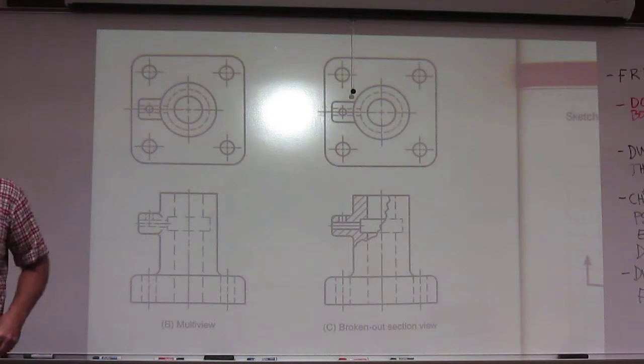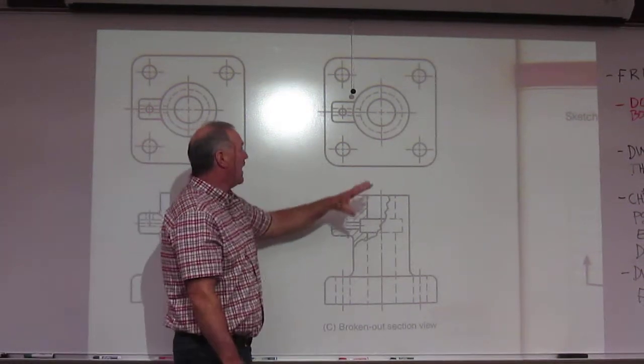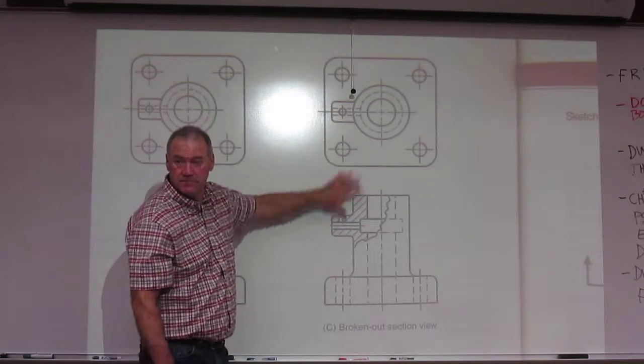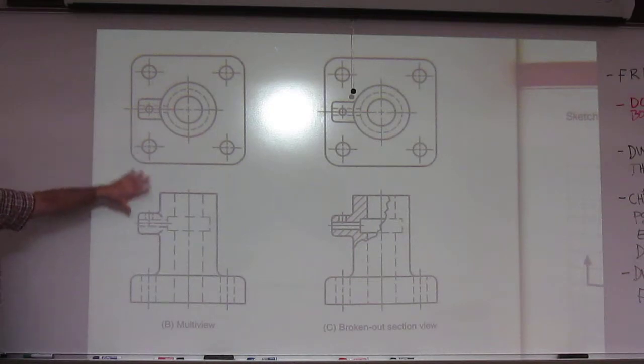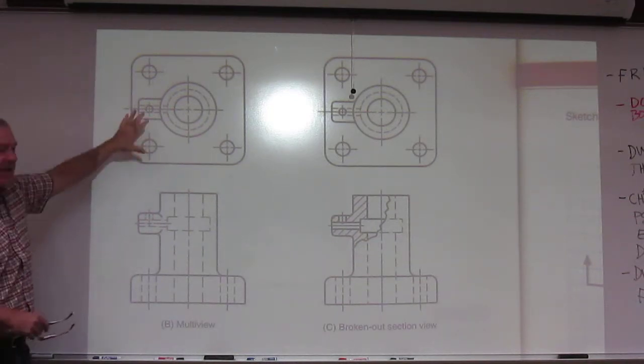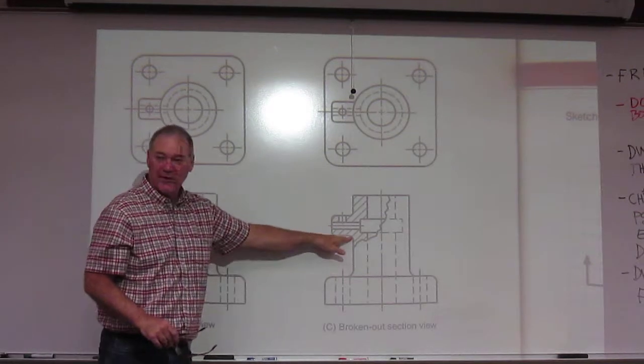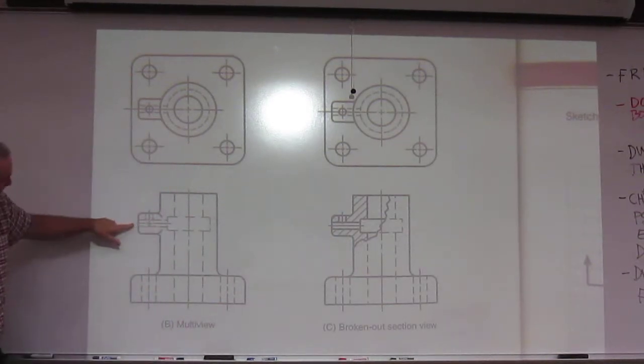Yes, okay, Lisa? So would you still show all these views? Well, this is just comparing and contrasting. I would show these 2. So you wouldn't know that. This is standard orthographic projection. Okay. So they're comparing and contrasting the 2 views. This is standard. This is with the broken out section. And you can kind of see the difference on what's going in here.